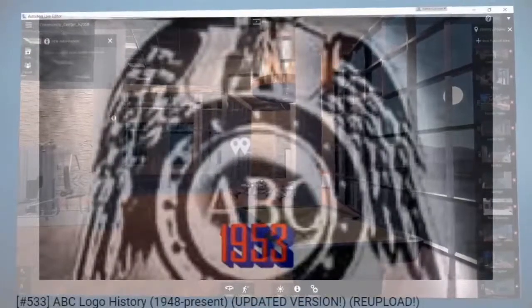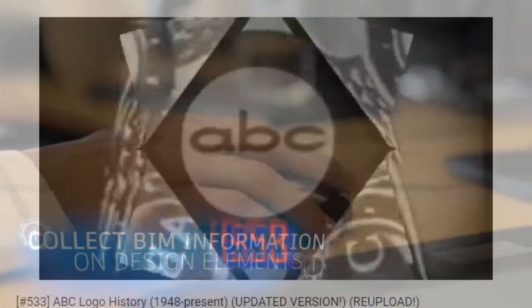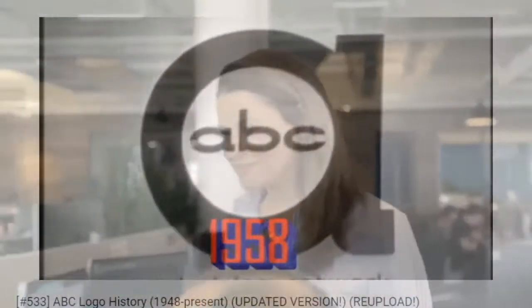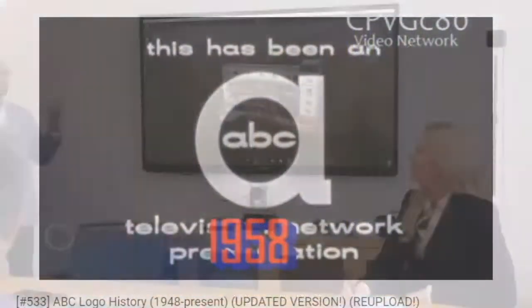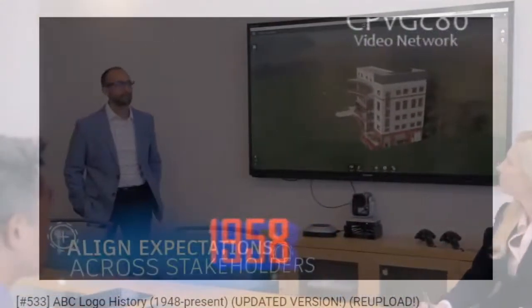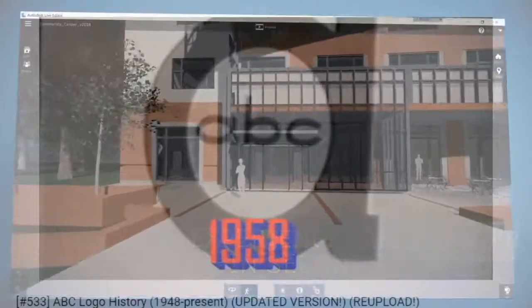All right, so I'm just going to hold that thought for a second. This view has its parameters pretty well set. Floor is only 3D view. I'm pretty comfortable with that. And that's pretty much it now. We can cut the geometry out as well. To actually cut it out, put in a mass in place and create any shape you want and just cut it out.